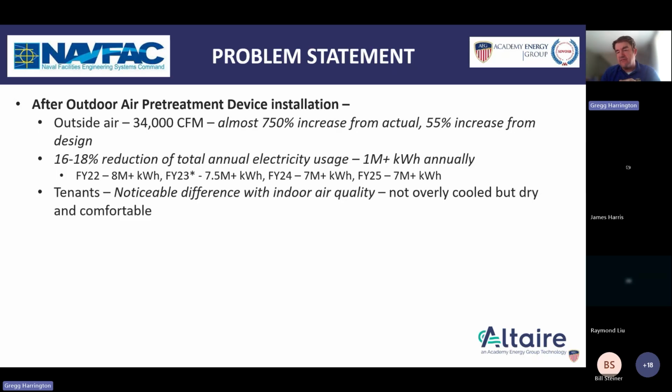Air handler savings alone for the unit that went through the validation process, we saw roughly a 40% reduction in energy consumption. And that's a significant impact at the AHU level, but trying to understand what was happening at the building overall, we were also able to get information concerning total kilowatt hours consumed.